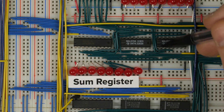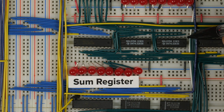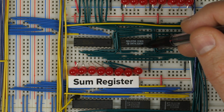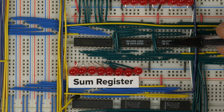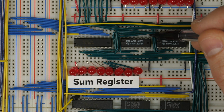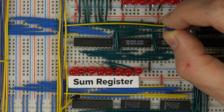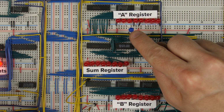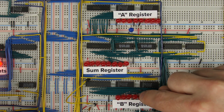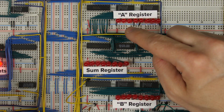So if the result of adding the first 4 bits doesn't fit in 4 bits, then we can carry the 1 into this 5th bit. Well, if the result of adding all 8 bits doesn't fit into 8 bits, there's another carry signal coming out of this second chip right here that we're not doing anything with yet. And just to see what that looks like, we can hook an LED up to it. So here we go. It's currently not set, which makes sense because we're adding 0 plus 0, and the answer is 0. And of course, 0 fits within 8 bits, so the carry bit's not set.